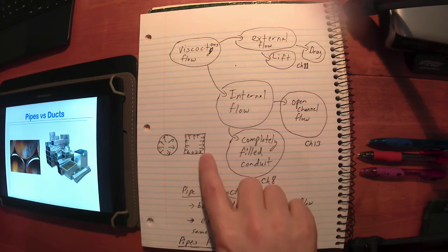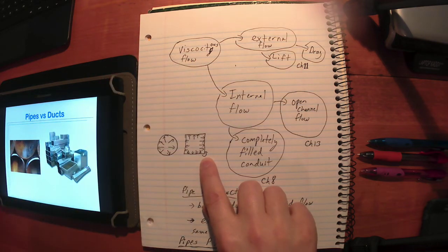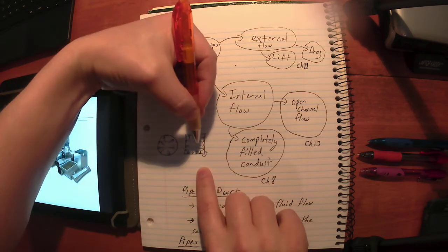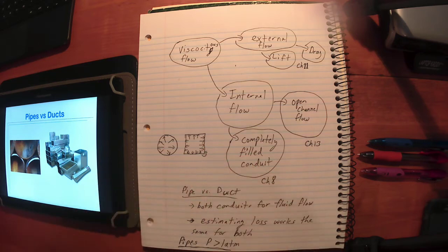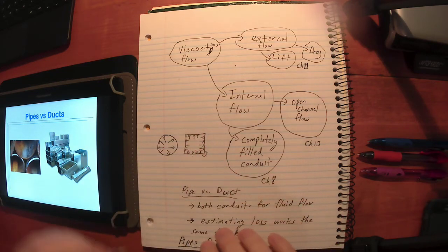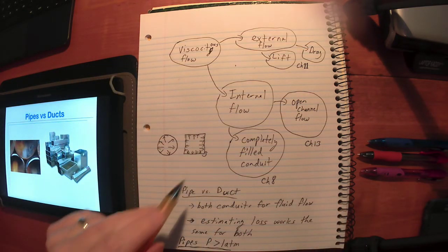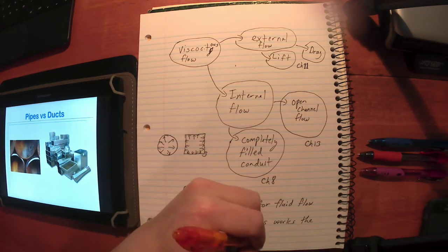Well, notice what happens here in the corners. You've got a bending moment caused right there in that corner because you've got some force pushing one way and another force pushing another way. You get bending moments, and if this pressure is large, you're going to get a stress point. A concentration of stress occurs right there in the sharp edges.